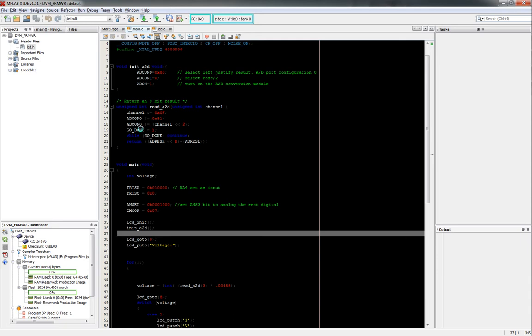And you'll see why, because the very next step, we OR in the channel that we've read in through our parameter and that we've masked off. Whenever you're ORing something in, it just basically adds it to it. So we want to make sure we clear it all to 0 before adding something to it, because if it's already got a 100 and we add 011 to it, we're going to have 111, not 011. So you've got to be careful there. So that's what this is doing.